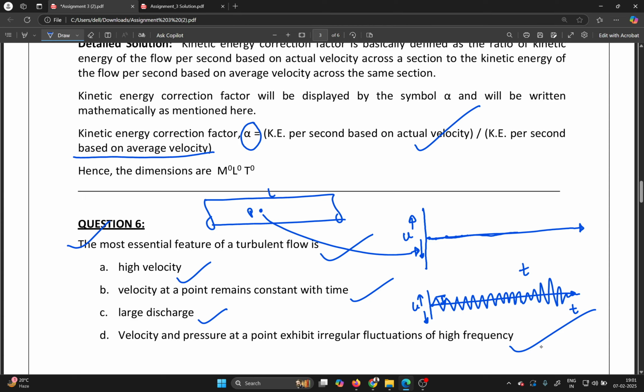And after that, for analyzing the turbulent flow, we need the approximate time average of the velocity. So when you average your velocity, if this is u, this velocity will be divided into your time average as well as the fluctuation.